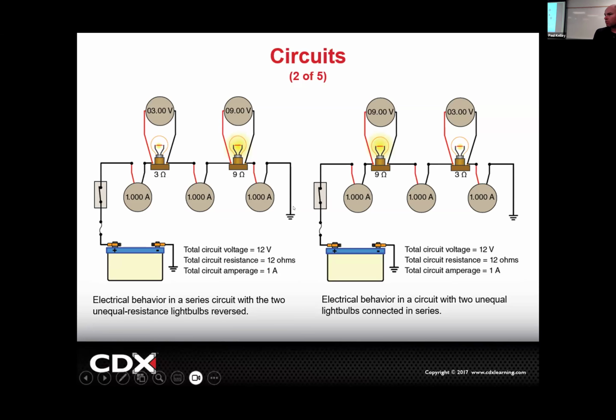Because we're going to have to do some experiments to make sure it does. Now, let's say I made this more practical. Let's just say, see this 9 ohm bulb? Let's say it wasn't a bulb. Let's say it was just 9 ohms of unwanted, undesired corrosion resistance.